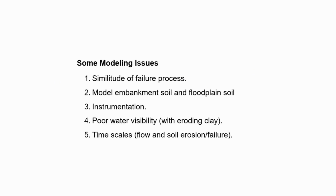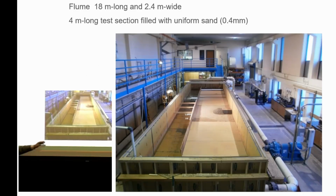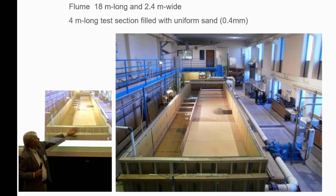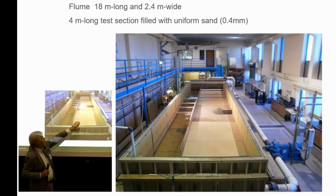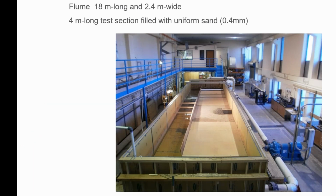So you can use wet sand as a model material, but you have to be careful about the timescales. Those are the background, but if we have an embankment, this is a flume in the hydraulics lab at the University of Wyoming, Clearwater Scour, we have an erodible tip on an abutment. What happens if we strengthen that abutment by adding material to the sand to make it stronger? We vary the strength of the earthfill.